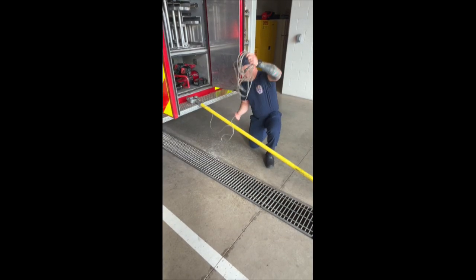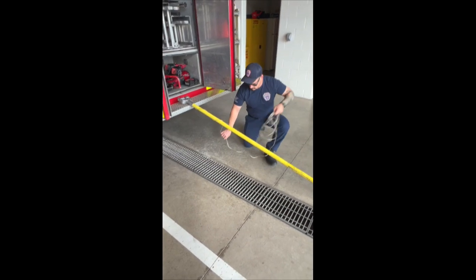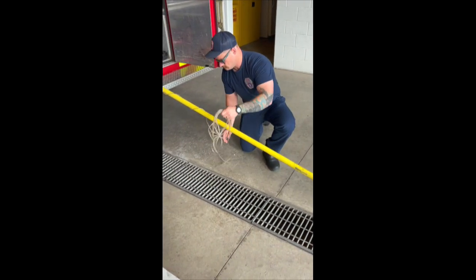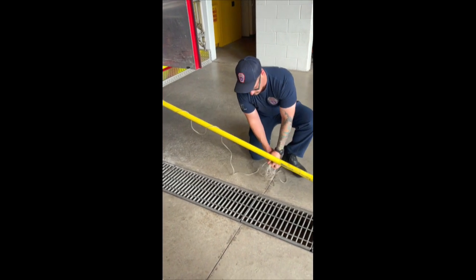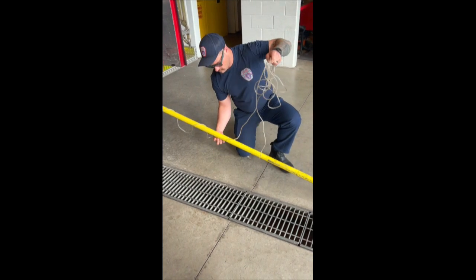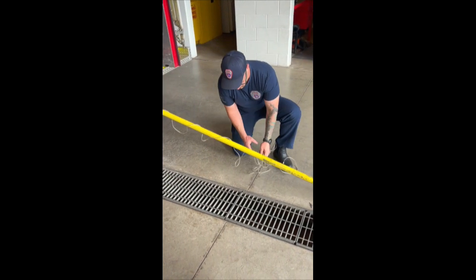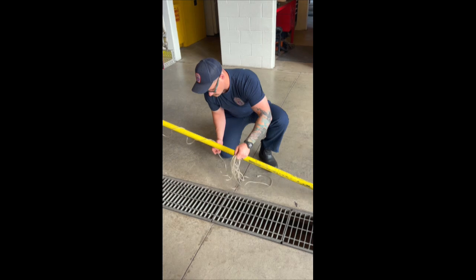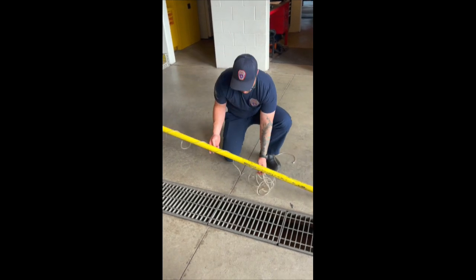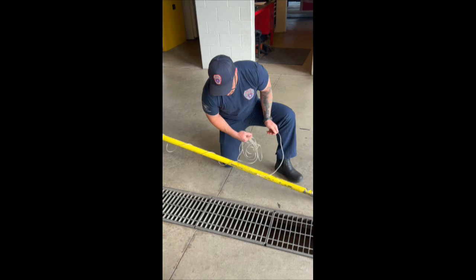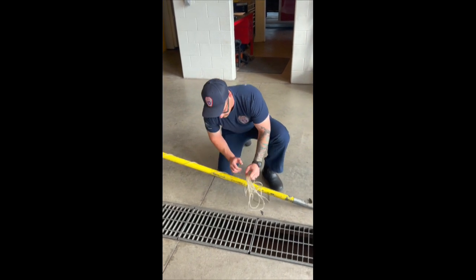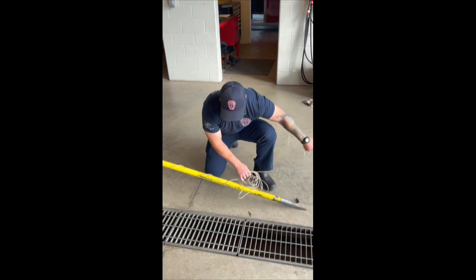At times it may also be necessary to monitor in a horizontal space that we may not have the reach for. In that case, we can use whatever available materials we have. In this case, wrapping the tubing around a pike pole to insert to the horizontal space of the vault to monitor that space either continuously or maybe prior to an entry team moving through the horizontal space into the next vault.